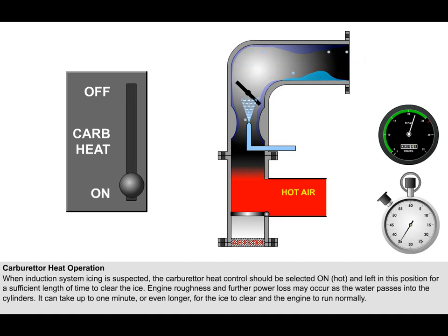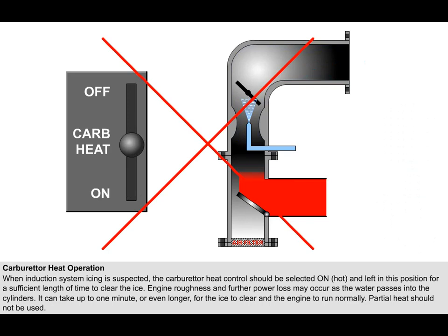It can take up to 1 minute or even longer, depending on the severity of the icing, for the ice to clear and the engine to run normally. Partial heat should not be used unless the aircraft is equipped with a carburetor air temperature, or CAT, gauge.